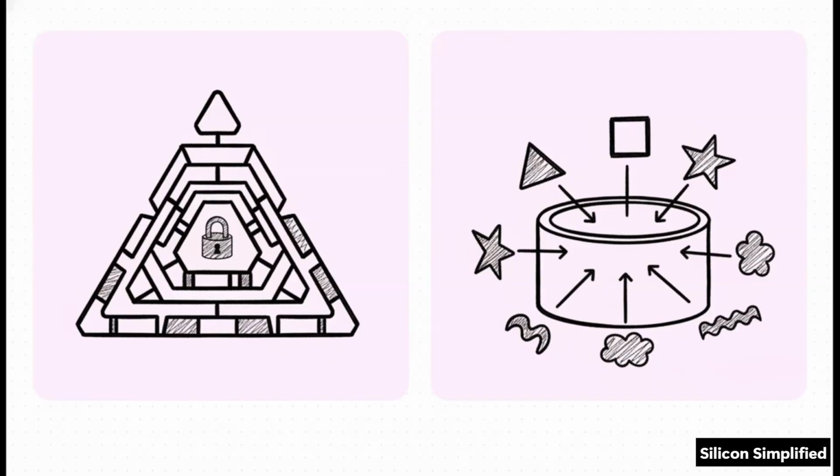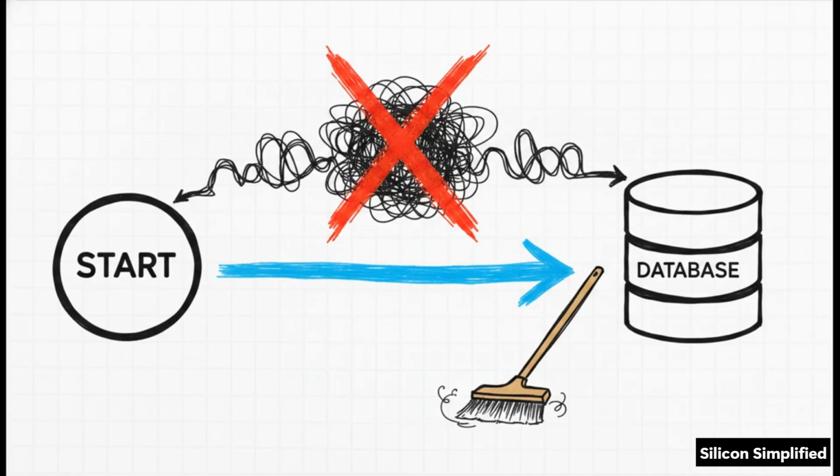Here's why. The config_db requires a very strict hierarchical component context, but the resource_db uses straightforward string scoping. That means you can easily access your configuration from anywhere, even from dynamic sequences that exist entirely outside the component hierarchy. So the ultimate pro tip takeaway here is that adopting the resource database eliminates one of the most frustrating patterns in all of UVM, that awkward p-sequencer macro. Because the resource DB doesn't care about component hierarchy, your sequences can just grab configuration data directly. You don't have to route it through a virtual sequencer just to get a component context. Trust me, it keeps your codebase exceptionally clean and modular.